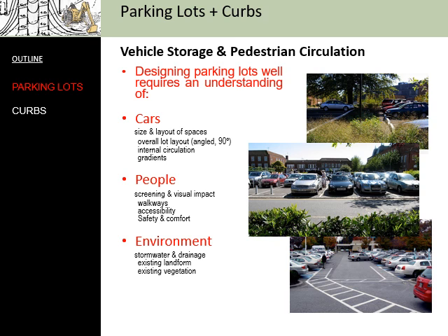So we need to be aware of things like the sizes of the spaces, the layout of the spaces, the overall layout of the design, whether it's rectangular or maybe it's at 90 degrees, what sort of medians and planting islands we might have, and then of course the internal circulation of the parking lot. Where do the cars run? Are they looping around? We want to avoid dead end parking.